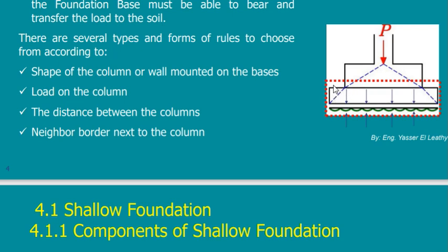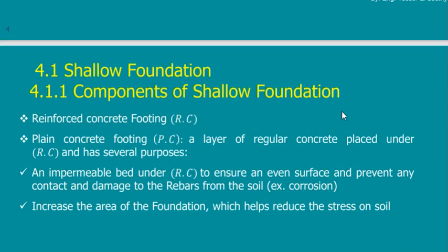You cannot have a cantilever, because to have a cantilever it means you have moment. If you have moment, then you need to have steel, but I don't have steel in the PC. So the maximum to go outside the reinforced concrete is just the depth of the plain concrete. I just give you an idea, but when we go to a section, you will understand it correctly.